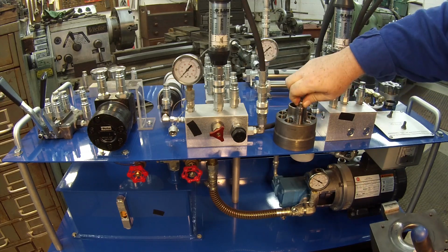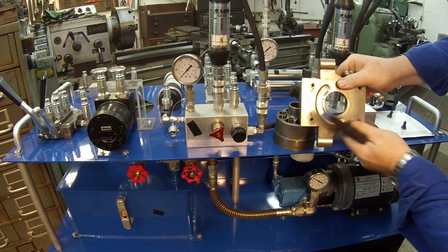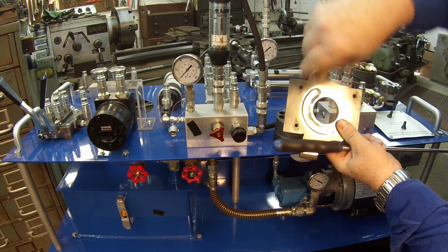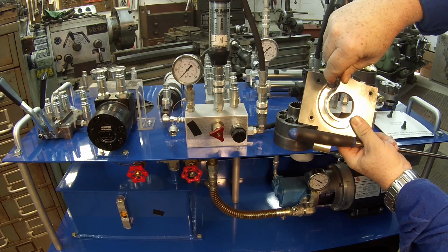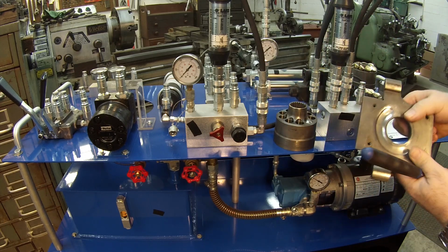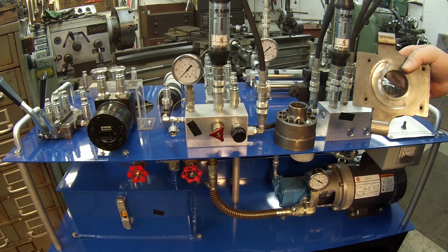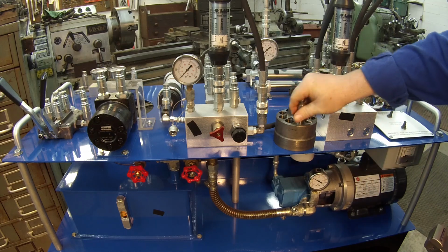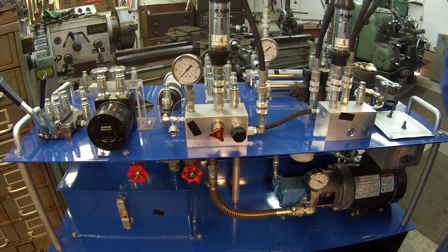Alright, so when those pieces come apart like that, this piston right here, the shoe came off and actually dug into this plate right here as it was spinning around on here, and that's the reason that it finally failed. Okay? So it's important to understand what cavitation, aeration, and those things do to your system. Very, very damaging to your system. Alright, let's hear what that sounds like.